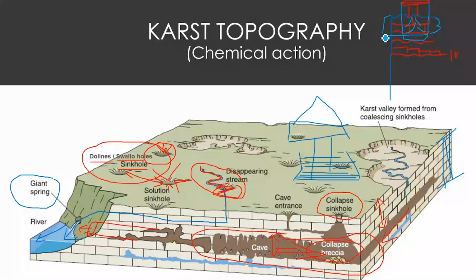So we sometimes have to find a solution for this trouble. What is the solution? The best possible solution is to go for a deep foundation. Deep foundation means we are going to penetrate the entire limestone terrain where the groundwater activity is there, and my foundation is going to rest on this rock. Now, a condition applies: this rock should be strong enough to take the load.